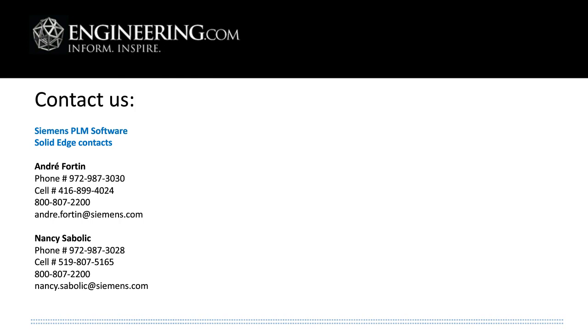In-context design is when you make relations between parts in the context of the assembly, and these are relationships that have to be rebuilt during the course of the assembly. So when you make a change in the assembly, it takes a long time to update the individual parts and then update the assembly. And if you make a change to an individual part without having the assembly open, then the associated part doesn't change, and you've got all these file management concerns that go along with it.